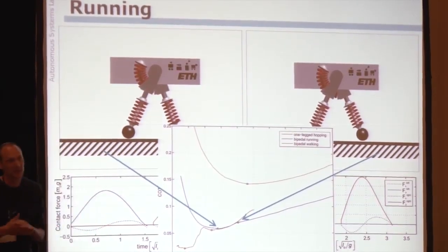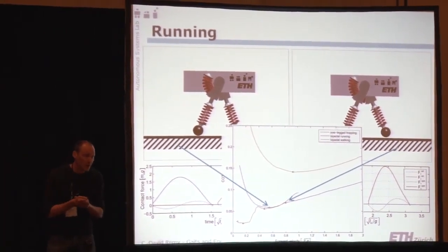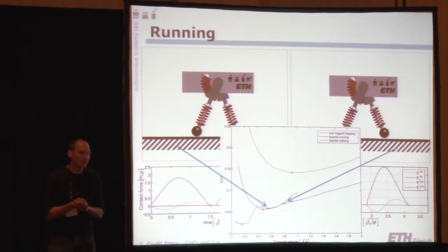It might be asymmetric. If you try to minimize mechanical power, it makes sense for the actuator to inject all the energy in the second half of stance. The reason is that you want to minimize compression velocities in the spring, which are proportional to your damping losses.